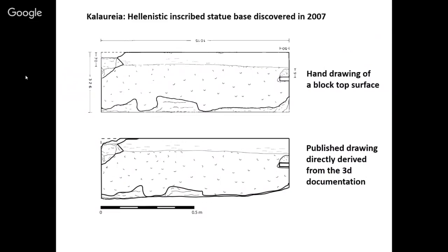as a rectangular block. There's a limited amount of measurements you can take when you do hand drawings. The top one is the hand drawing, and the bottom one is the subsequent total station drawing of the same block. You can see that with the lower right corner, it's no wonder that the blocks don't actually join. Discrepancies of 5 to 10 centimeters are quite often what you can expect in hand drawings of blocks, and especially when they're broken, they get very, very difficult to make drawings of.